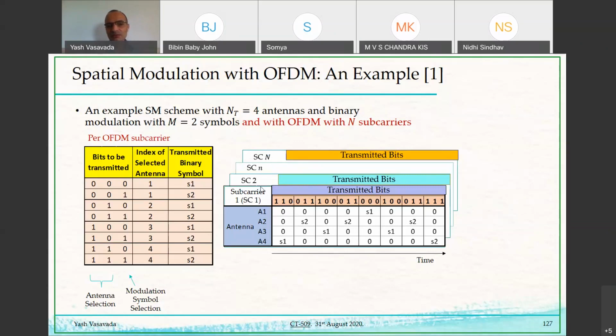But what is happening to the bandwidth now? Compared to the bandwidth of one subcarrier, these capital N subcarriers will collectively occupy N times larger bandwidth. Right? So the ratio doesn't change. So it will not be correct to say that my spectral efficiency is increasing. On a per unit of spectrum, I'm still transmitting 3 bits. But what this scheme allows me to do is, if I have more bandwidth, then I can put more and more subcarriers, and effectively I will get higher data rate. Does that make sense?